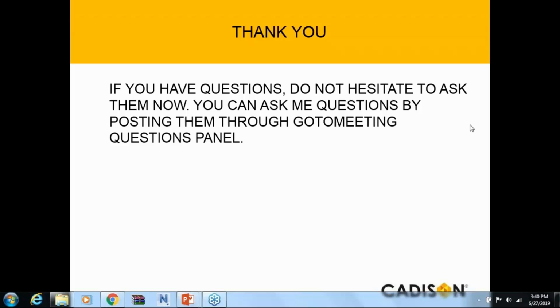In case of smart plant, you can achieve this by the tool that they have called the smart plant interoperability, but between PDMS and CADISON it would be just exchange of graphics. So the answer for this would be that no, there is no ready-made integration between PDMS and CADISON.